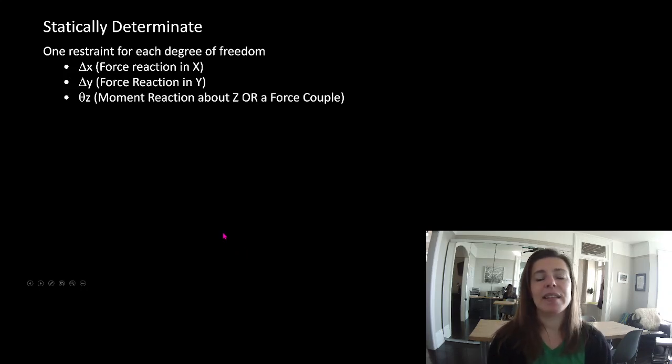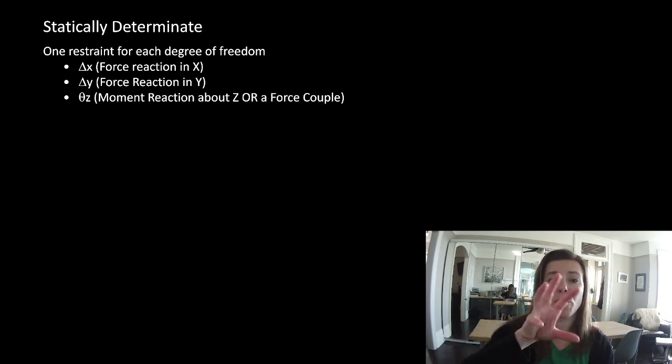What does statically determinate mean? Statically determinate means there's at least one restraint for each degree of freedom. So there is a force reaction in the x direction, there is a force reaction in the y direction, and there is something that stops it from rotating.